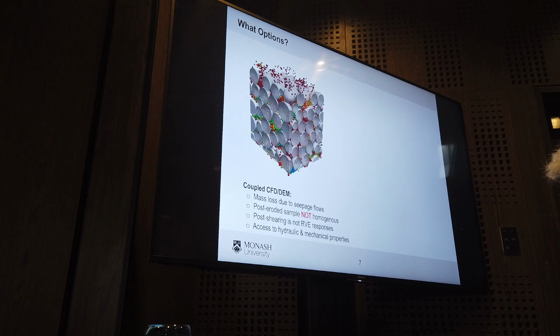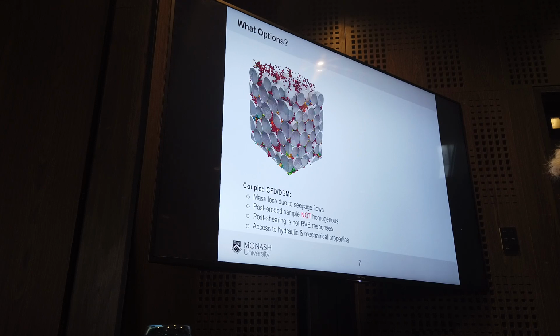But the other option we could do is to look at using a numerical tool to actually investigate this internal erosion process and how the mass loss affects the mechanical consequences of the sample. We can use the CFD-DEM simulation. This is one of the works done by my PhD student, fully coupled CFD-DEM simulation at different scales, and you see how the mass loss is transported through the whole system.